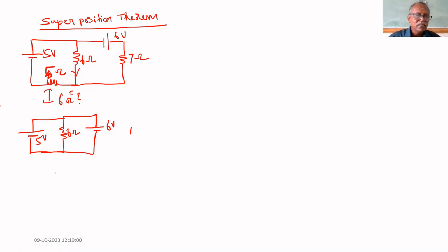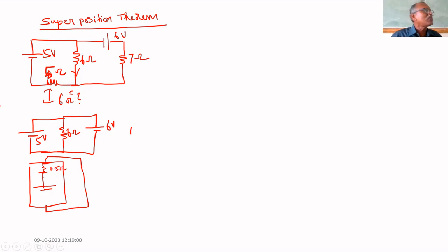Suppose I'm having this battery. Internal resistance must be mentioned in series with the battery. So the battery is this, and the internal resistance will be inside. Inside, you are taking terminals like this. You are short circuiting, but anyhow the internal resistance of 0.5 will be in series with the circuit. Already I told in the previous example that the resistance may be anywhere in the path. The same effect, whether it is inside or outside. We have seen that in KCL. So this and this are the same.